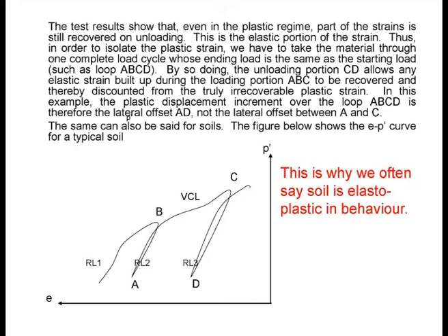Basically, yes, there is a small amount of hysteresis in soil. You always have that in that kind of loading and unloading situation. But when we are talking about the recompression line in classical soil mechanics, we usually regard it to be the same as the swelling line. So, in a sense, the recompression index is the same as the swelling index.